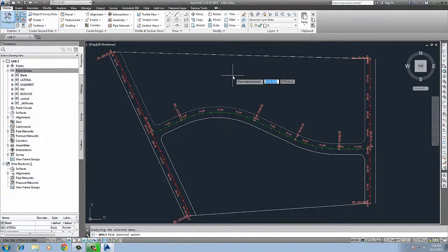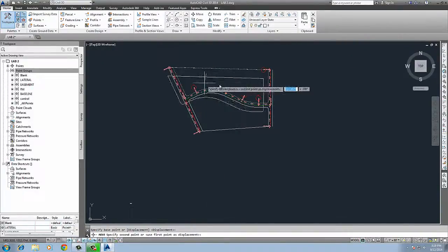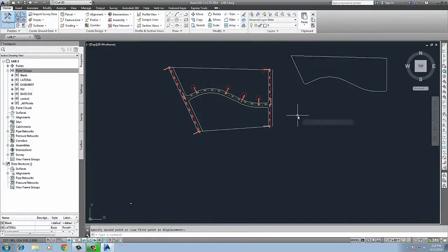Okay, it did not. And notice what you should be getting is a dashed line. That's indicating that that's going to be your polyline. Sometimes it requires a pick in a location over here or over here, so it will fail if you don't have a completely closed boundary or if you're just picking in the wrong spot. But once you pick that, just hit enter, and what you'll notice now, if you click up here, you have a polyline, and I can move that thing actually. It's not going to affect anything. That actually is the polyline representation of that area that it found.